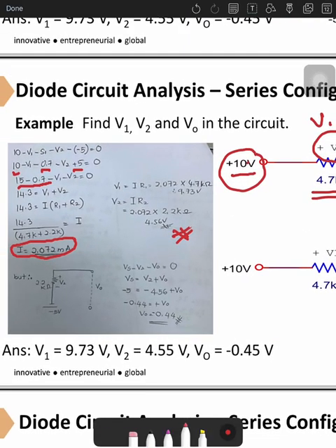So you have the Vs. As I mentioned, the first source is the highest potential, and then minus the V2 and minus the V naught. So you rearrange, you can get the Vs equal to V2 plus V naught, and Vs is negative 5. That's why you substitute here: negative 5 is equal to V2 plus V naught. What is your V2 just now? Your calculated V2 is 4.56. So why is it negative? Because of this one, plus the V naught. So overall you can get this value.